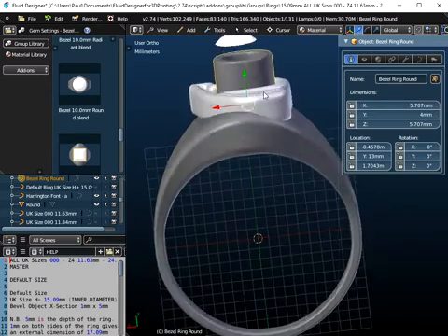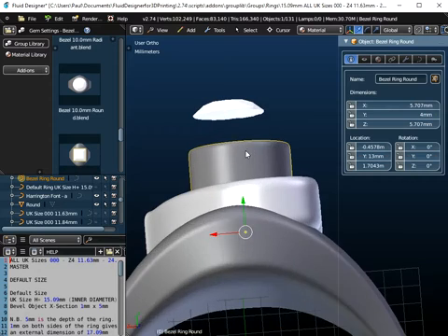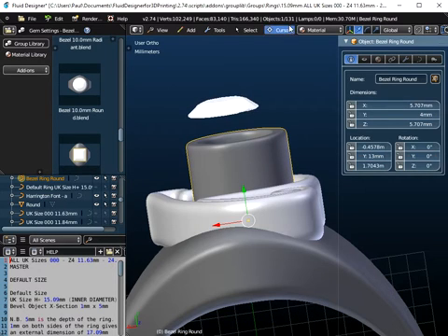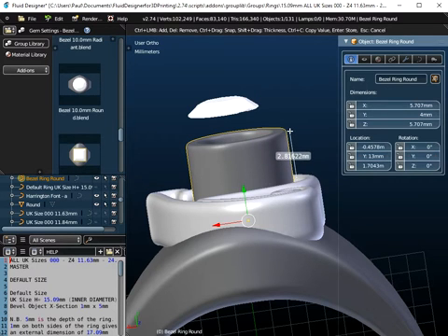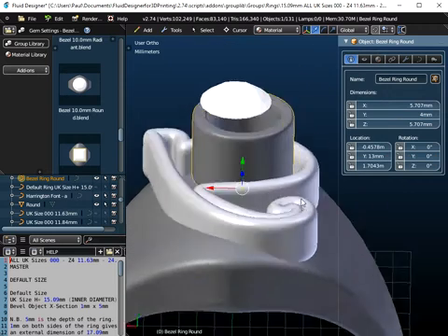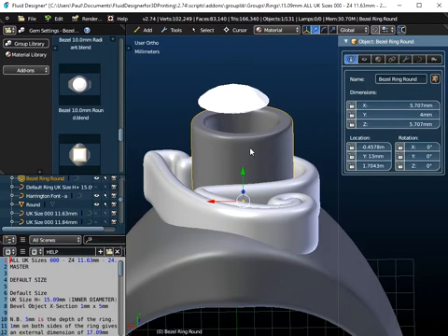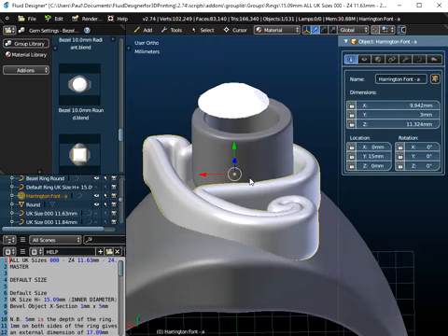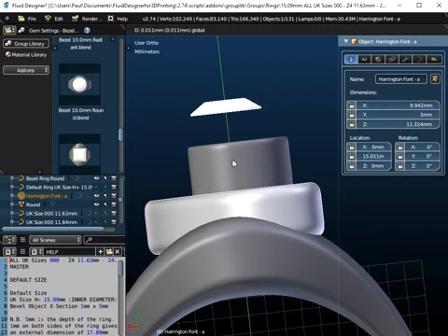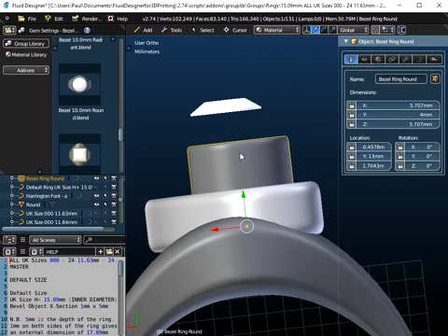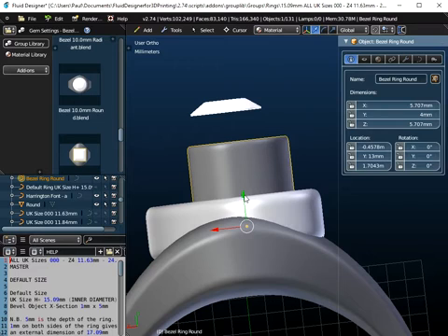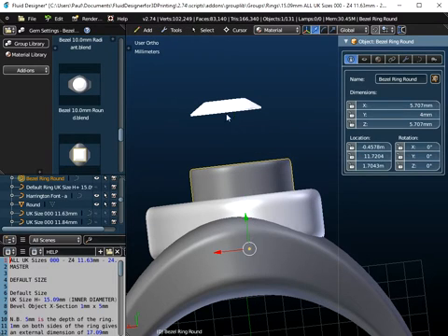Yeah, that seems okay. Now clearly the height that you've got on this, and remember there is a ruler on the toolbar, you can measure this height. So at the moment it's 2.5 millimeters. That height is going to depend upon the gem that you've got. Okay, so you may want to adjust that height. Oops, I've got the wrong object selected there. Let me just put the A back where it was. You may want to adjust this height depending upon the gem that you've got, and I say there is a ruler so you can measure that.